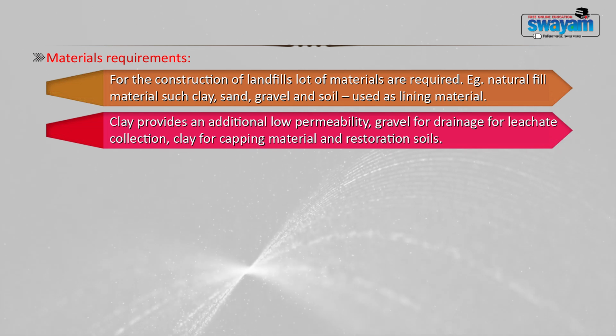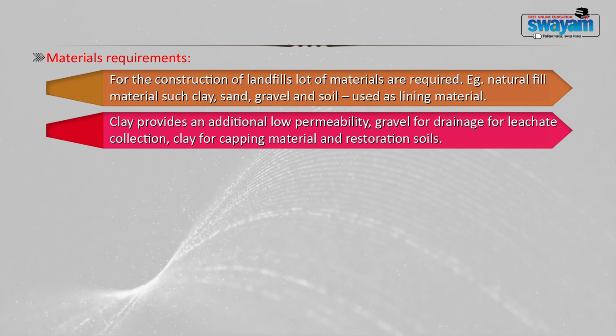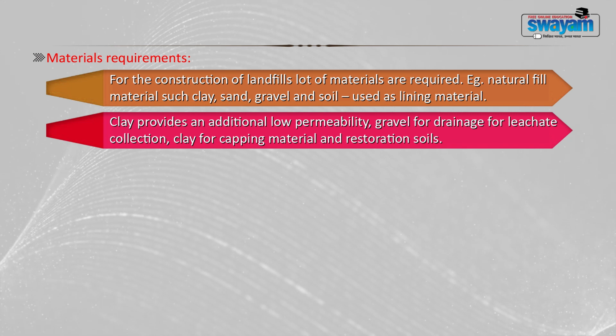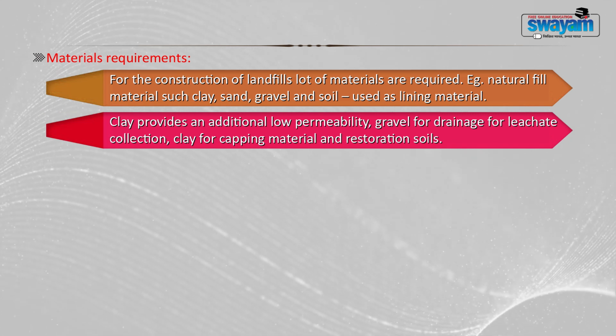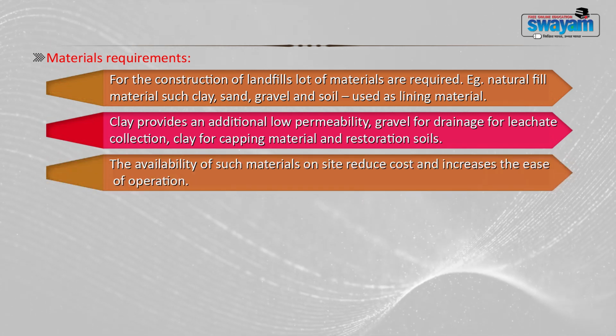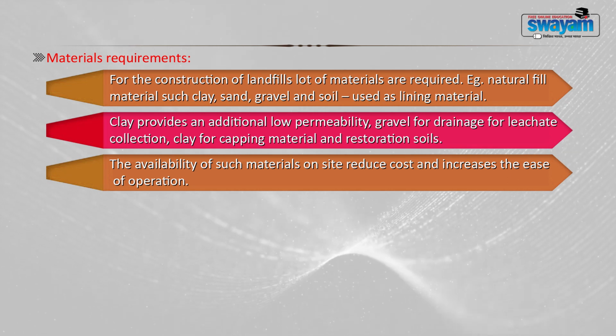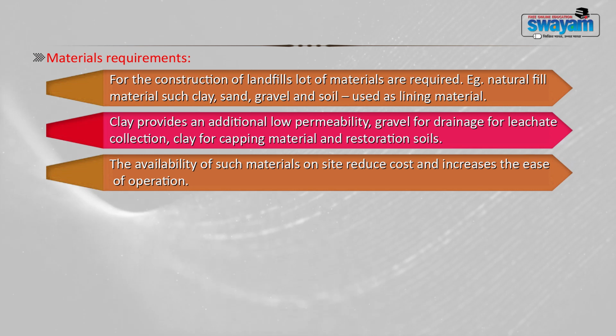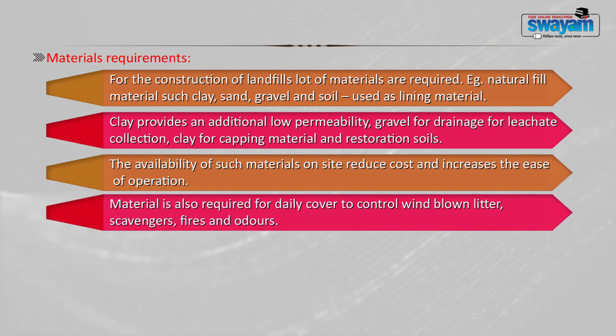So, wherever you select a site for constructing a landfill, you should see whether the land or the site itself has these materials, or at least they should be available in the close vicinity. Now, if these materials are available near the site, it will reduce the cost and it will increase the ease of operation. The material is also required for daily cover to control wind blown litter, scavengers, fire and odor.